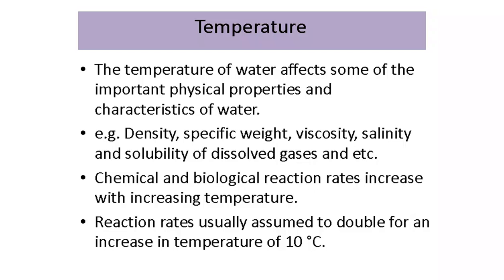Here we have a continuation of temperature. The temperature of water affects some of the important physical properties and characteristics of water, for example, density, specific weight, viscosity, salinity, and solubility of dissolved gases and some other materials. Chemical and biological reaction rates increase with increasing temperature, and the reaction rate is usually assumed to double for an increase in temperature of 10 degrees centigrade.